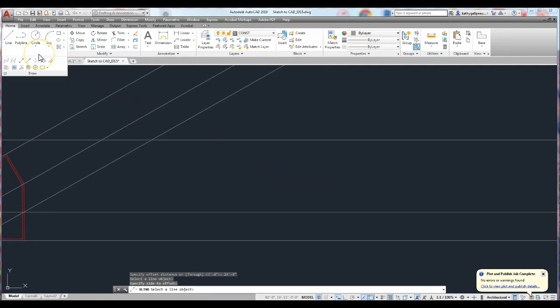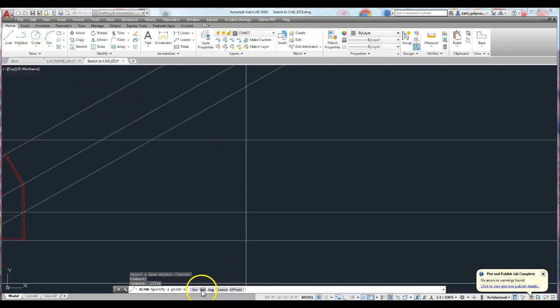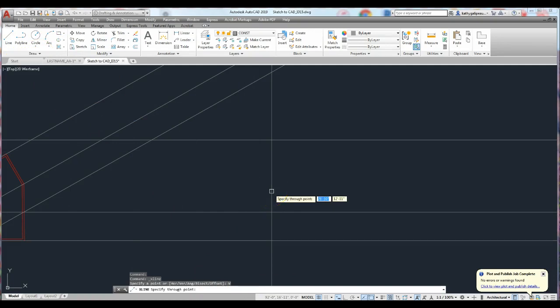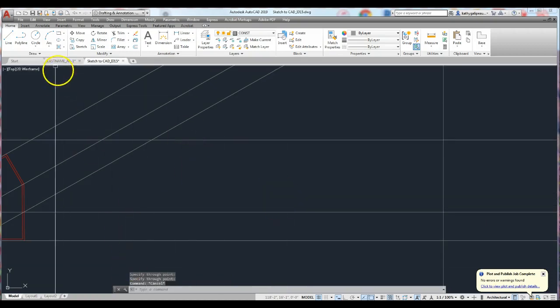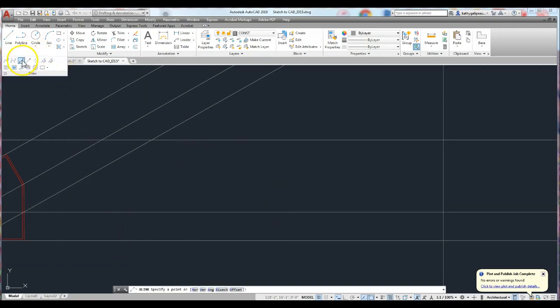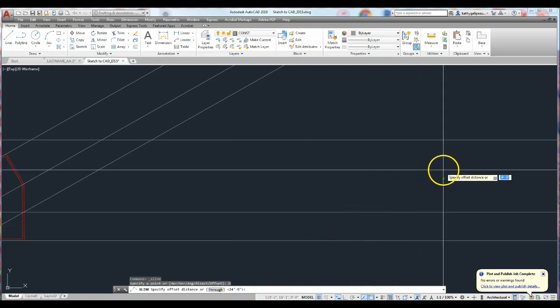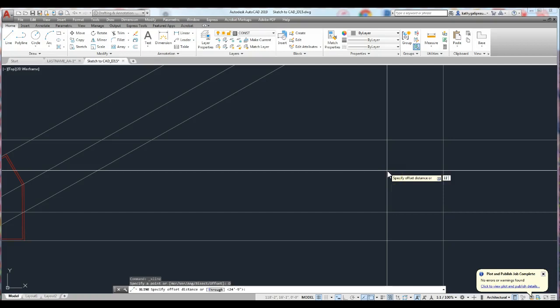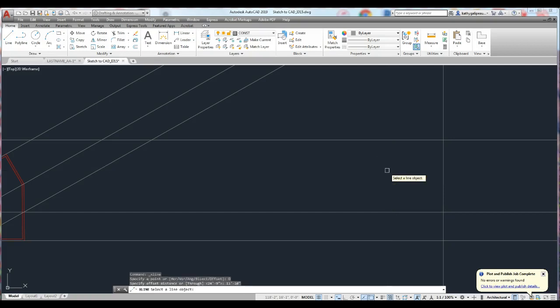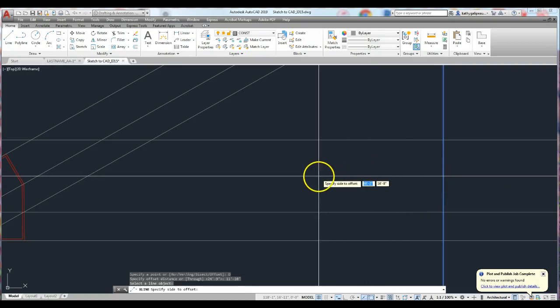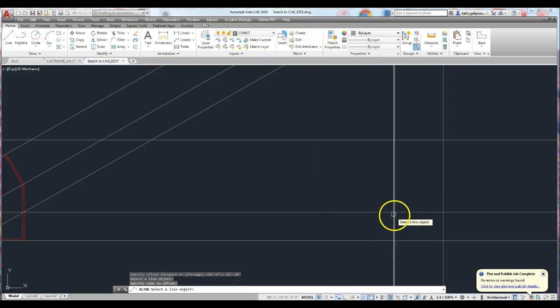Then let's put some vertical lines in. So construction line again, click on vertical, and we can set this one, let's set it off to the right, and we're going to offset to the left this time. Enter, and again, construction, this time we're going to offset, and our distance away from this far end wall is going to be 11 foot 10 inches. Select the construction line, drag inward, and click. So there is our first part of the plan.